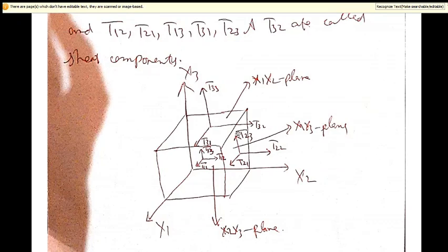For a vector you have three components, and here we have the traction vector, a force. Stress is also force, second order. Stress is basically internal forces, a second order tensor. These internal forces are the second order tensor. Traction is a vector force which has three components, and the stress tensor has 9 components.